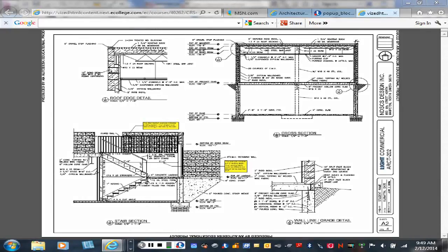So, like I just mentioned, if our overall wall was 12'8" to the top of this exterior masonry wall, then the things that are getting covered up are the steel beam that has to be incorporated into the wall between columns, and then the bar joists that sit on top of that beam. Now, steel bar joists are different than wood joists, in that typically they are top chord bearing bar joists. Okay? So they hang off the top of the beams.